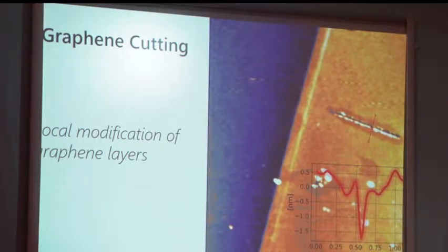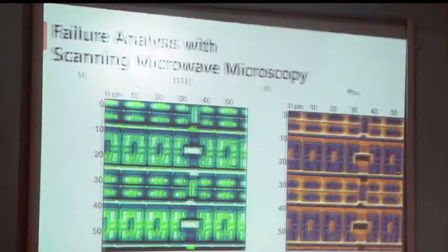If you want to do some sort of manipulation, let's say here somebody has demonstrated how much force is required to cut a graphene layer, demonstrating the stiffness of the graphene layer. So this is one of the measurements from one of the US universities. But anyway, such kind of lithography is also possible, where you apply force or voltage, and then you scratch and measure what force is required to cut something, what is the stiffness of the material. That is also part.